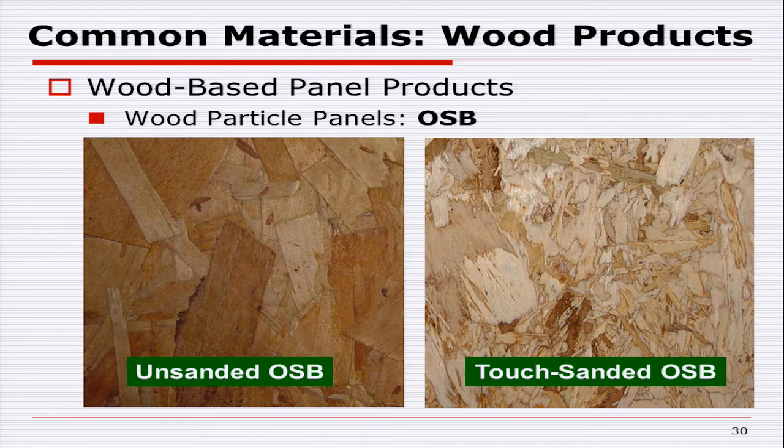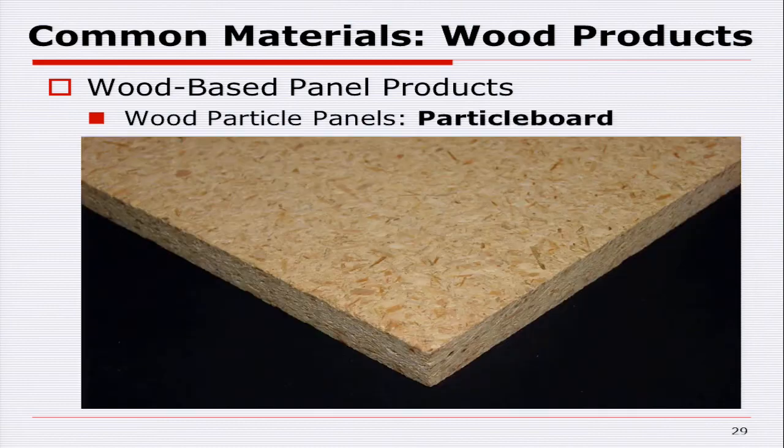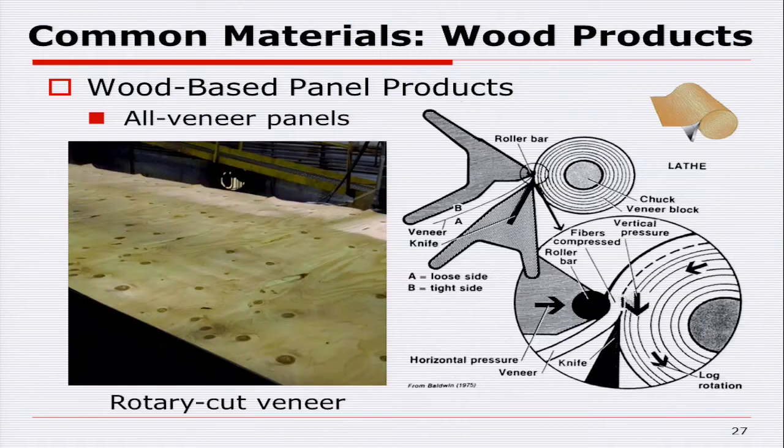The reason that we make this product is there are a couple of reasons. Number one is in place of plywood. To make plywood, you have to have complete veneers. Understand that when you first start peeling a log, you don't get a full sheet like this. Logs are tapered, and when you start running that knife edge, you're only hitting the log at a few spots. You have to get in a little bit before you start getting a full sheet off of there. So all that first stuff is just garbage.